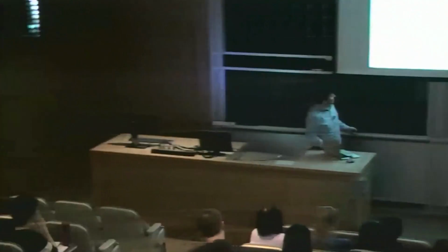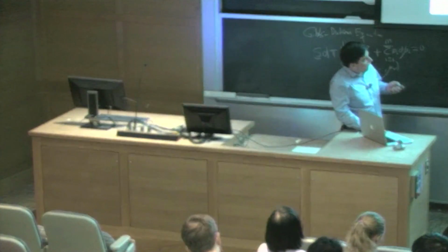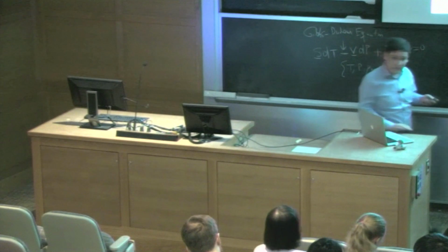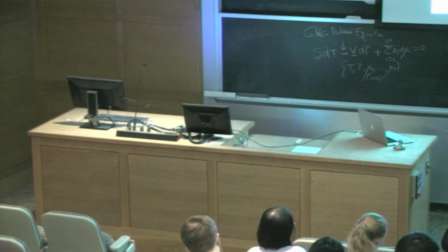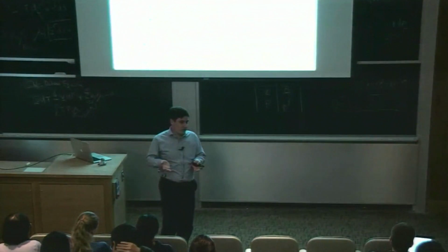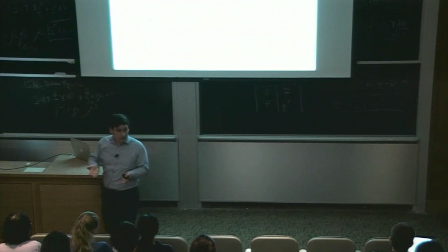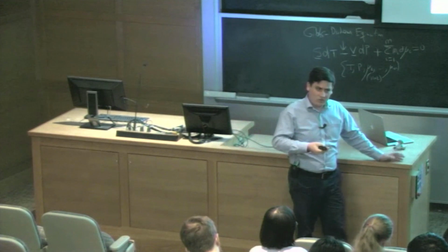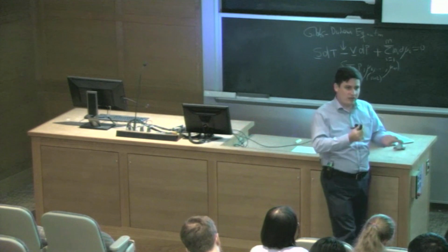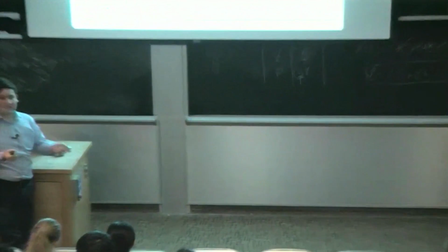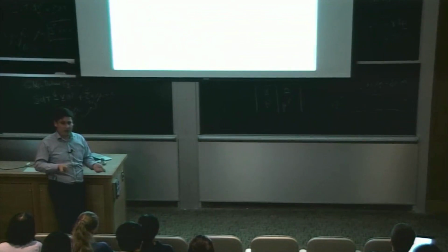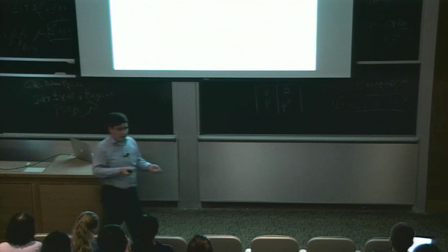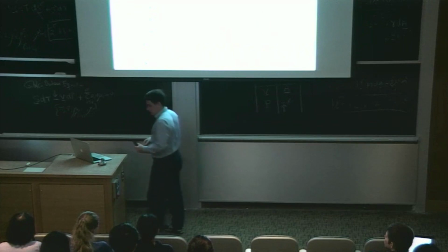So these pop up all the time. You see them in models of reaction networks where we try to use a pseudo-steady state approximation. We say some reactions go so fast that they equilibrate, so they're not governed by differential equations, but by algebraic equations for equilibria. They can pop up in models of control where we neglect the controller dynamics. Say I'm going to try to control this process, and I get to instantaneously turn on or off this valve in response to a measurement. Well, actually, controllers have inherent dynamics in them. But if I don't put those dynamics in, then I may get an algebraic equation instead of a differential equation for how the control process occurs.